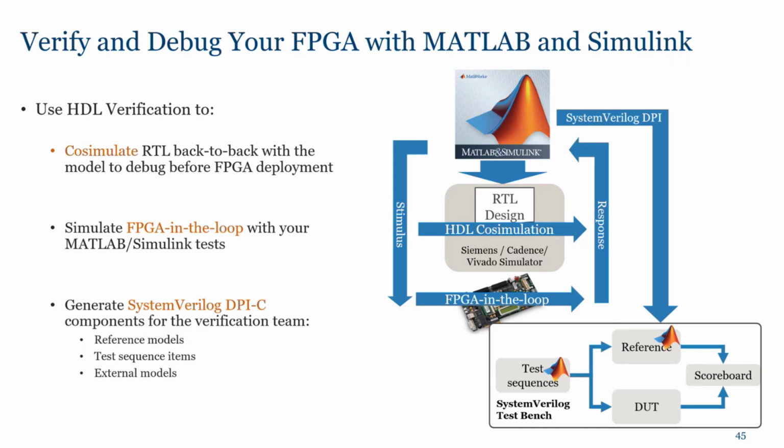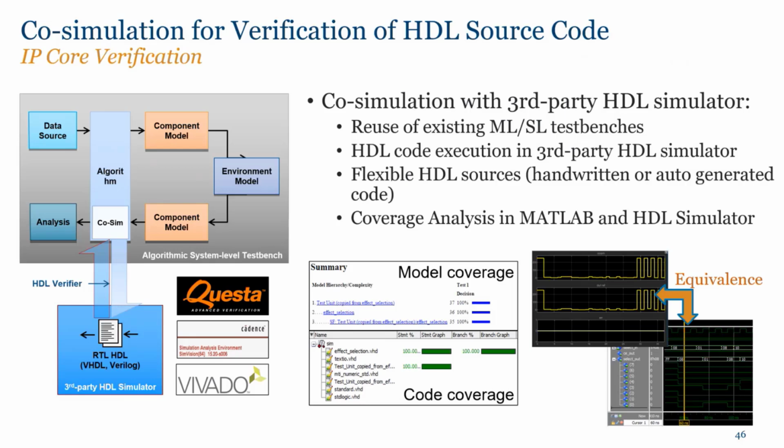We can also generate SystemVerilog DPI-C that we can provide for the verification team, who can use this SystemVerilog DPI-C to generate test benches for the reference, which will of course be in SystemVerilog DPI-C, and to provide the same test benches for the DUT, and later on compare the results outside of the MATLAB and Simulink environment, in order to compare the result between the reference and the DUT or the RTL design. So we'll go through co-simulation, FPGA-in-the-loop, and UVM later on in detail.